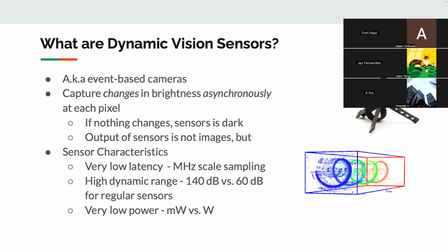And basically the motivation behind these dynamic vision sensors is that they work more like how the human eye works. Your eye doesn't actually see a constant image. It sees only the change in your image, as each neuron in your eye fires asynchronously when it has a magnitude change or a color change that is interesting to it. So these sensors work by that same basic principle. They only activate when they see something of interest, when it crosses some threshold that's appropriate, which is tunable.